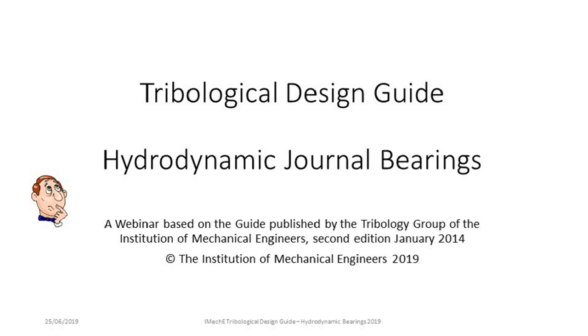Yeah, I mean if you're thinking about polymers or marginally lubricated bearings, obviously the one that everyone thinks of is PTFE. Well, PTFE has potentially a very low coefficient of friction, but it's not a low wear material. It tends to wear out rather quickly. So it's not always the best polymer. Well, it rarely is the best polymer to use. Depends on the application. But these things are always a compromise.